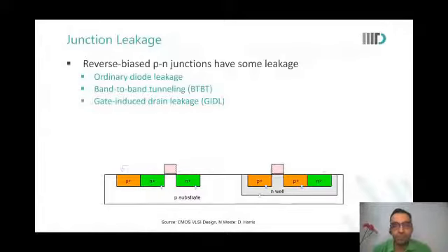So this body bias, in some places it is to our advantage when we talk about leakage, but wouldn't it create non-uniform currents, and that will lead to some unexpected behavior of the device? Because substrate is not directly connected to the source, this means that if I stack my transistors, then they will all have different VTs at different points of operation. So wouldn't that change the current through each of those devices?